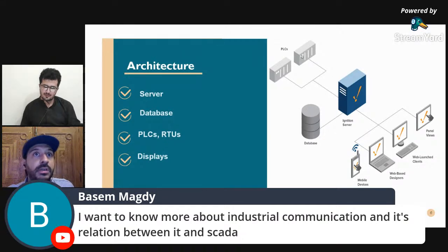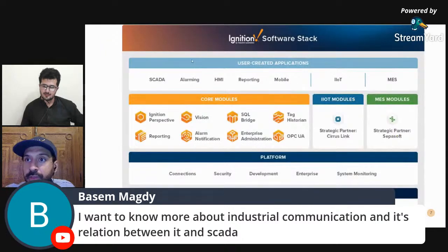The other thing is OPC. OPC is a standard where sometimes you have an OPC server built into some of the PLCs. For example, some ABB PLCs have OPC UA servers built into them, and the Ignition module, this module right here, the OPC UA module, is able to communicate with it directly.